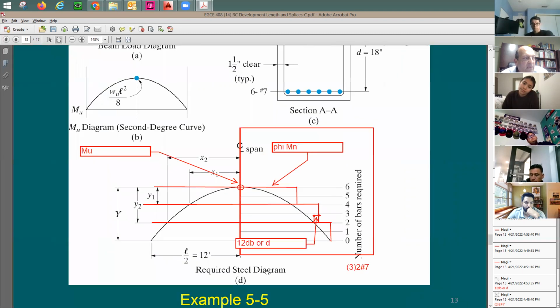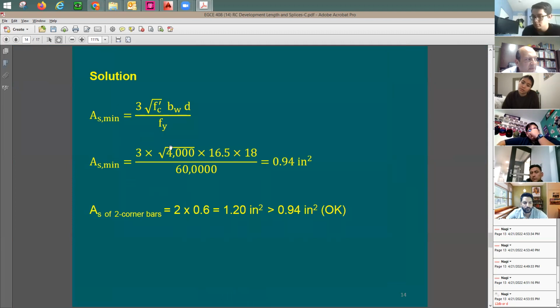So then I start by saying, okay, let me cut 2 rebars here, 2 rebars there, 2 rebars there. I'm just assuming that 2 rebars should be enough, because someone's going to come back here and say, how about this section here? Do you have minimum reinforcement satisfied? You say, you know what? Let me check. This is the reason that you're doing here this AS minimum, the standard that we do in beams.